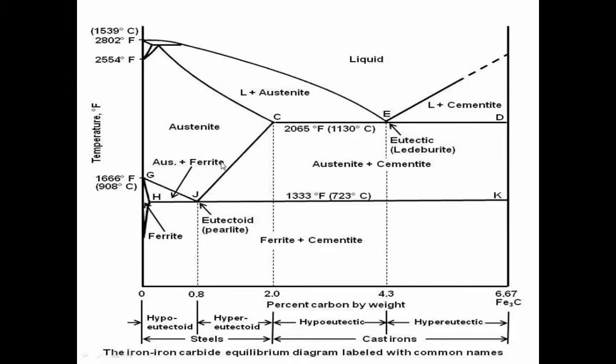Ferrite phase has a body centered cubic crystal lattice. If you cool further, the austenite phase will convert fully into ferrite phase, and depending on the carbon composition, it could also convert into cementite phase, which has iron carbide Fe3C composition, or ferrite plus cementite, which is called pearlite. So whatever the composition may be, there could be different phases when we cool it down.